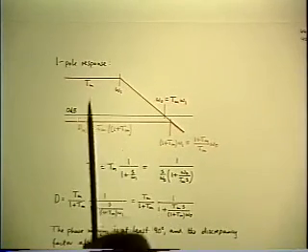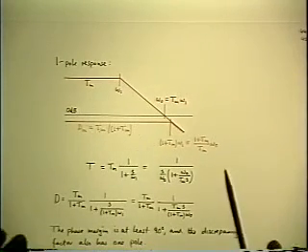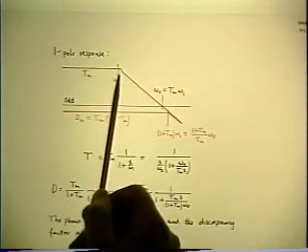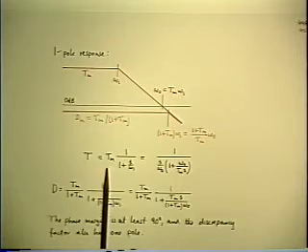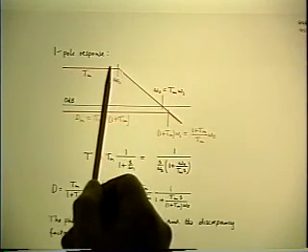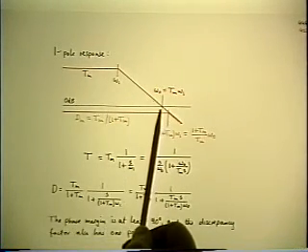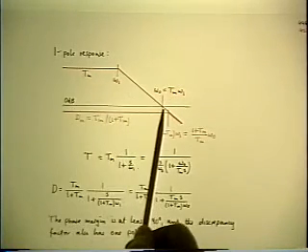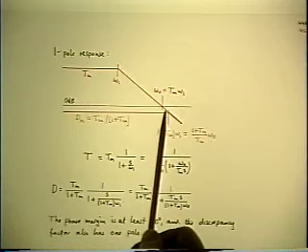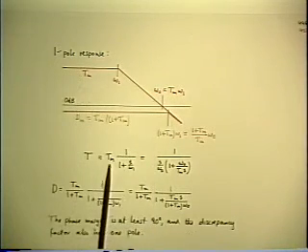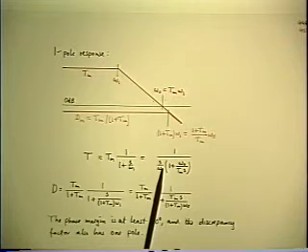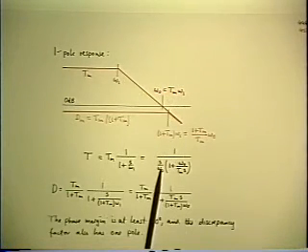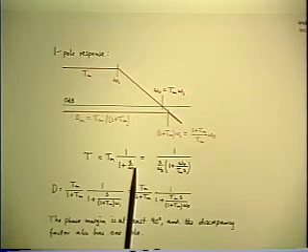We can do it graphically, which is basically what I just did, or you can set it up analytically by changing the parameter which we used to represent the original T. That is, by gain bandwidth trade-off, the crossover frequency omega 0 is equal to Tm times omega 1. So get rid of omega 1 by using that substitution, which converts the formula for T into this one.